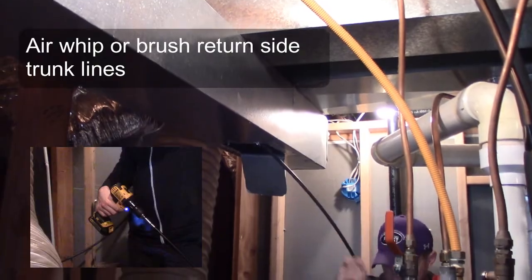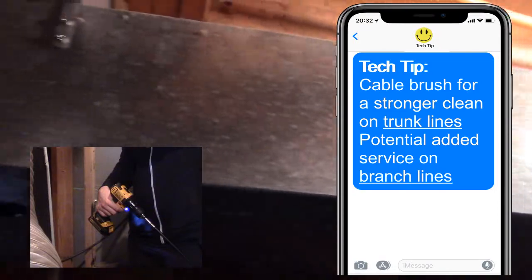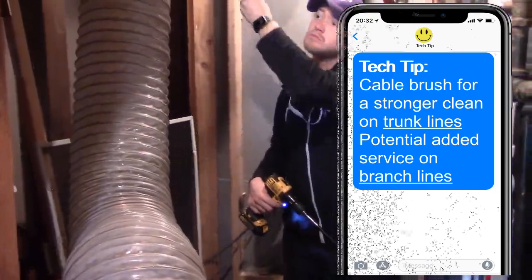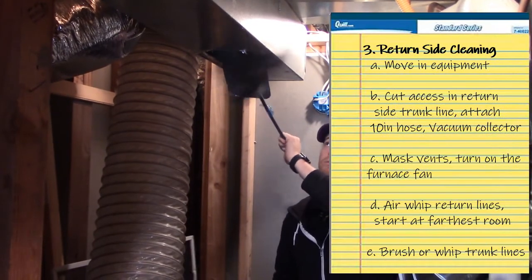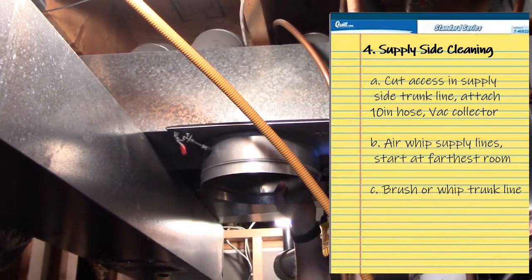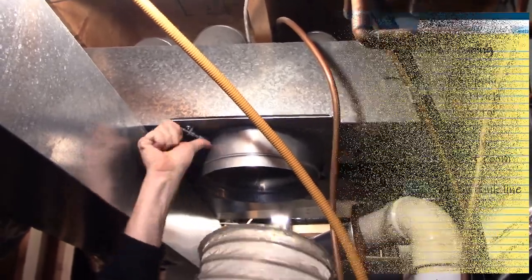Air whip or brush return side trunk lines. Here's a tech tip. Cable brush the trunk lines for potential added service. That's it for return side cleaning. Get your equipment set up, run the furnace fan, and air whip the brush and return lines. Next, set up and clean the supply side. Attach your 10-inch hose, air whip the supply lines starting at the furthest register, brush or whip the trunk lines.